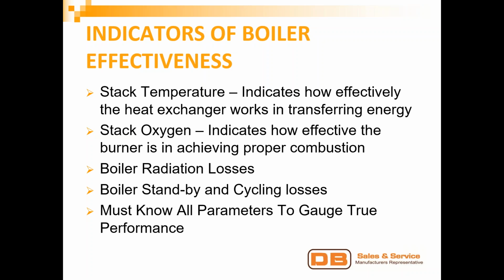Now, we do have other things to fight here in Southern California as well, such as low emissions and ultra low emissions, and sometimes that drives the stack oxygen up as well because we have to lower that flame temperature so we don't get as much prompt NOx or other NOx formations in there, lowering our overall emissions. So we do have a little bit higher stack oxygen here, but in general, the higher the stack oxygen, the less efficient your boiler system is going to be.